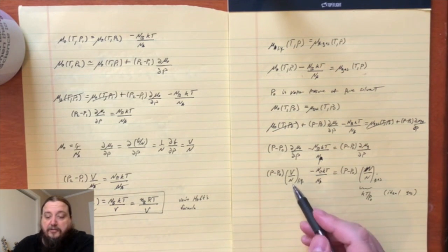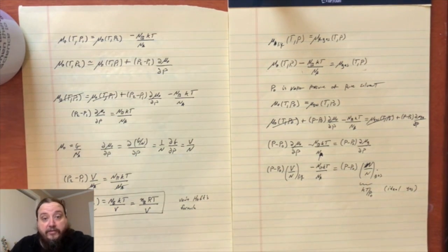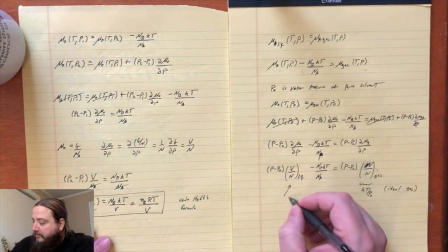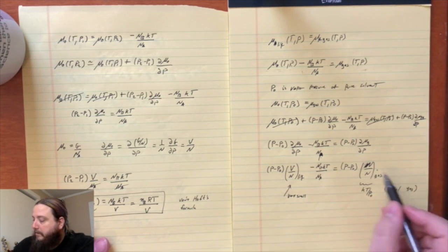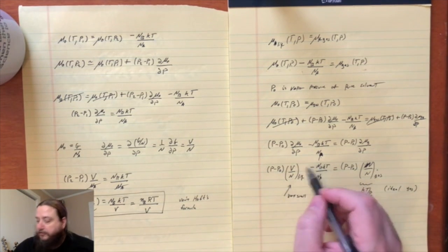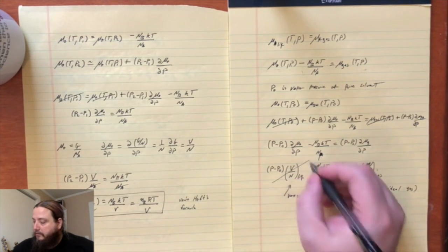And as a first approximation, we're going to assume that the liquid phase is very, very much denser than the gas phase, which is true for most boiling phase transitions. And so we're just going to assume that this is very small compared to this term, and essentially this first term here will drop out.